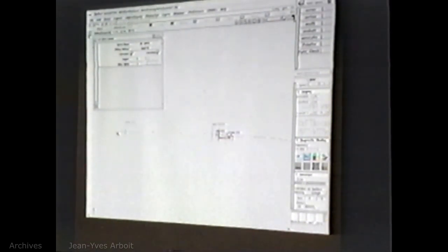But then you can also do a number of curves while you're still in this function, and there's history while you're in the function. So I can still go back to this curve and make modifications to it. And the idea here is just to be able to fit nice curves for the geometry so that you can continue to make better looking surfaces from it.